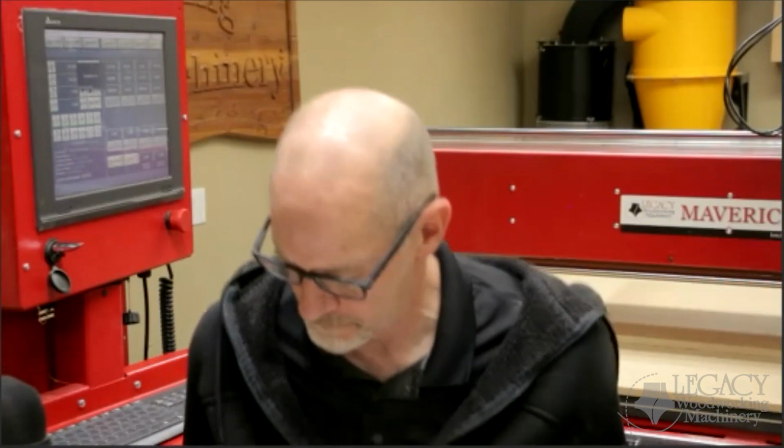This has only happened to me once, but I always anticipate it. I'm in Mach 3 on a 3x5 Maverick, and the tool came down and touched the smart pad and then stopped. It didn't raise up, it just stalled. The only thing I could do was pull the smart tool pad from under the tool.